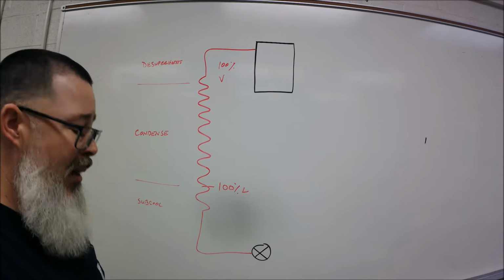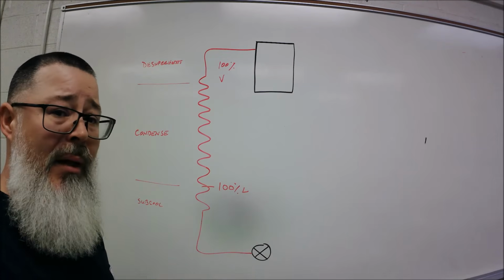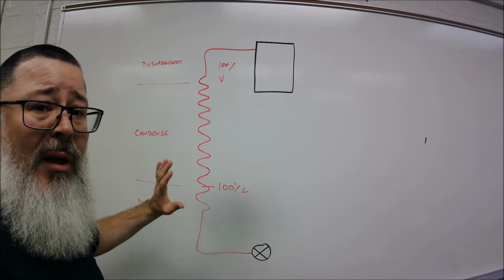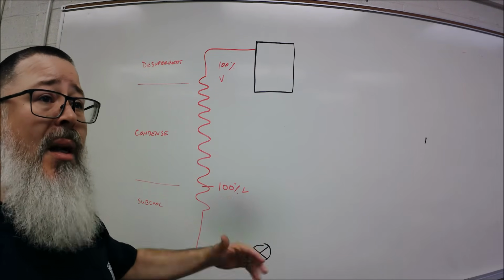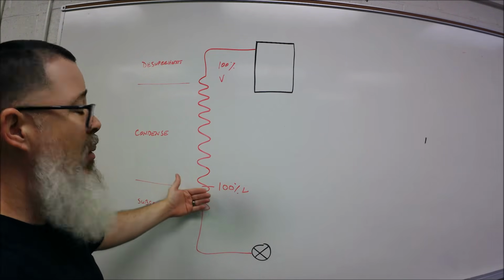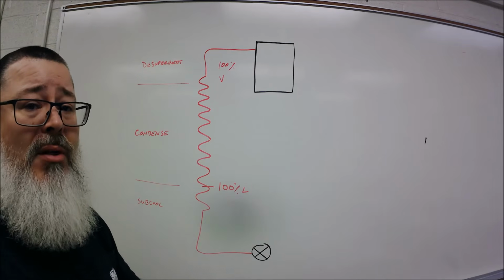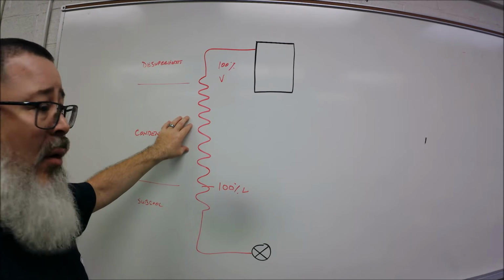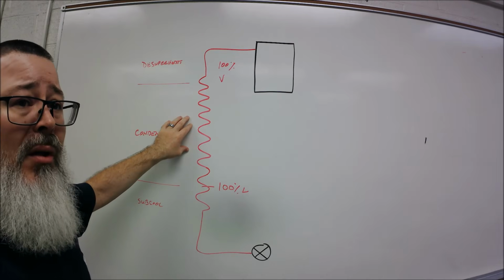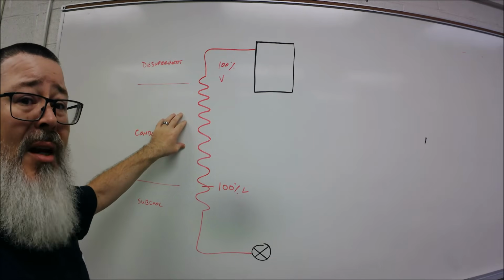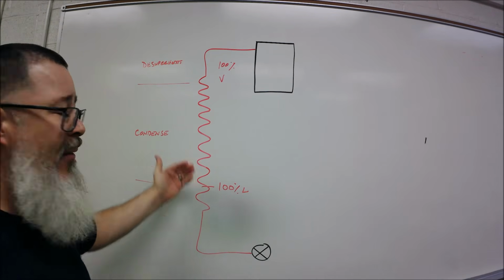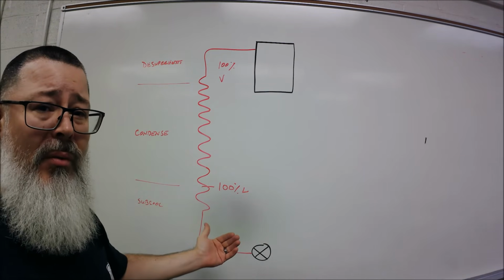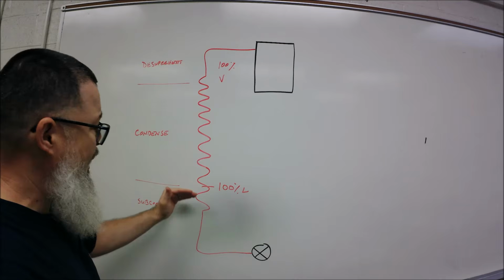What is subcooling? Subcooling is cooling of this refrigerant liquid below the saturation point. Superheat is heat above the saturation point. Subcooling is cooling below the saturation point. So if we had a 340 psi high side pressure, that's a 105 degree saturation point. Once we make all liquid, we still have a little bit of the condenser coil to go through, typically, right?